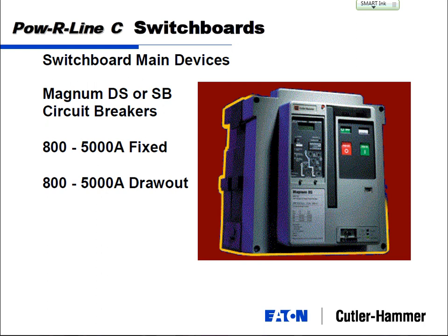Now, why would this be handy? Think about safety, an arc flash. If you're standing in front of a piece of switchgear, opening and closing a breaker, it's a dangerous situation, and it may say you need to wear the full protective suit with the helmet, the face shield, and everything. Versus here, I'm now 30 feet away, and I'm out of the blast zone. Maybe I'm even around the corner, and they can do it in whatever means that calls for, but it's going to be less.